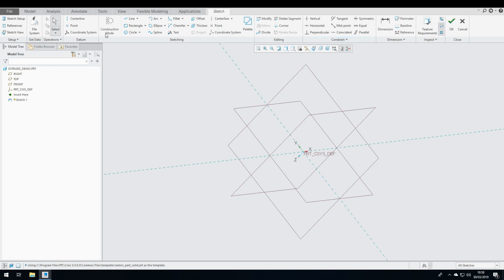If you select the plane first and hit sketch, it'll automatically do it. If you hit sketch first, it'll ask you to select a plane, so it doesn't matter which way around you do it. That was just out of habit. As you can see, it's given me some axes to draw on that go through 0, 0, 0. To line them up, there's a feature in here called sketch view. I always call it the J magnet because it looks like a magnet and a J, although that is just showing you the flat plane up from the solid model.